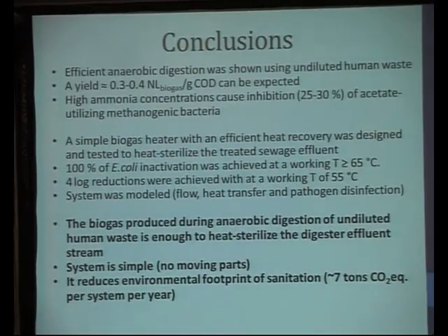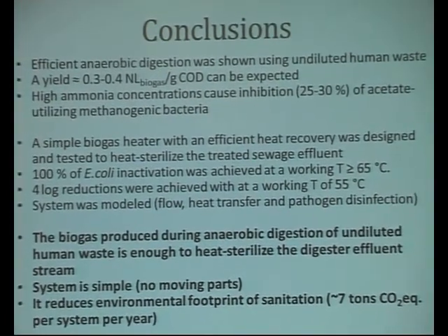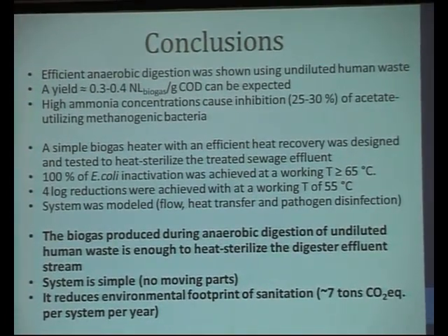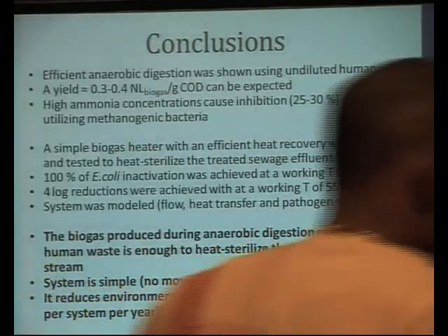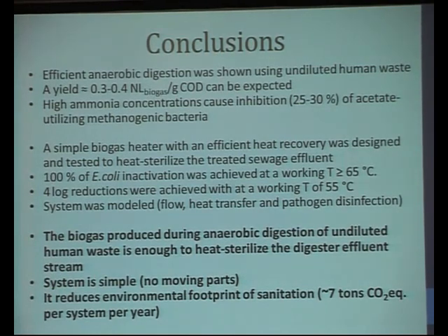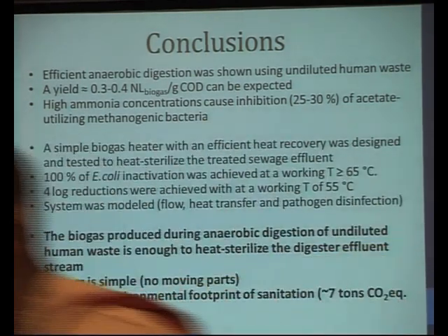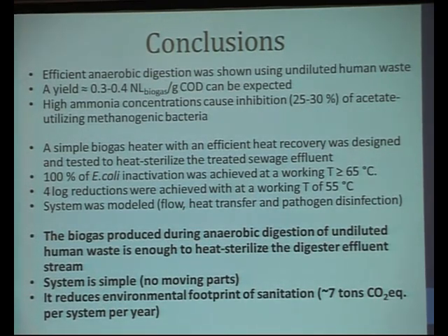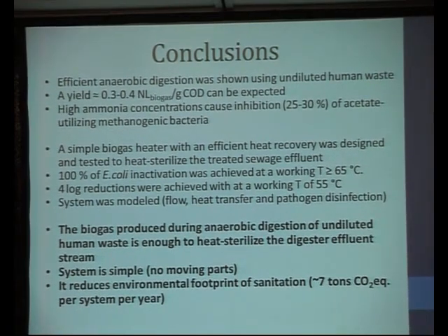So I'll just come to my conclusion slide here. In summary, what we've shown is we can effectively conduct anaerobic digestion with concentrated, undiluted human waste, and we're getting some pretty decent biogas yields. There's an issue with ammonia that we have to deal with, and depending on our current result, future ongoing work, we may think about some things like urine diversion to diminish the ammonia load. We've designed and tested a heat recovery system, and it's working pretty well.